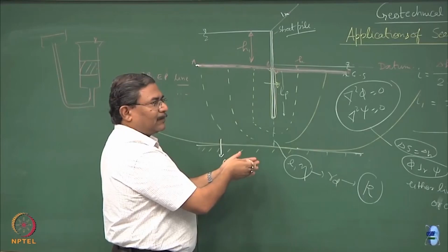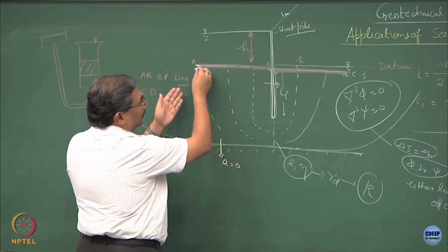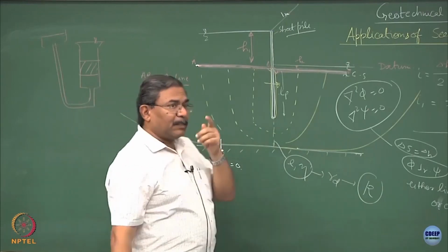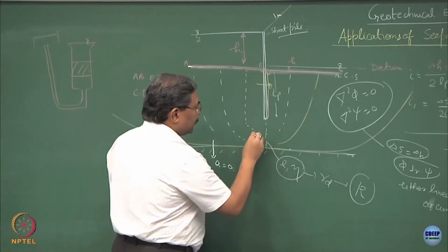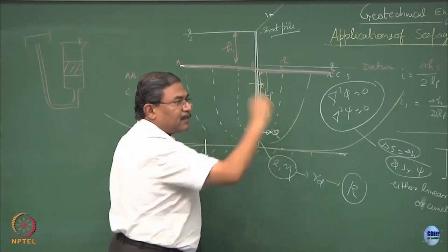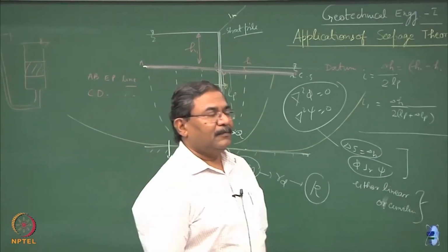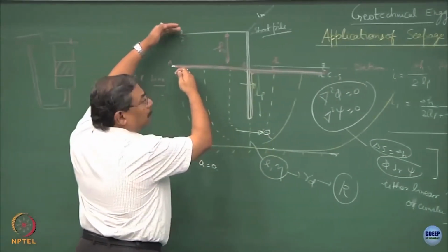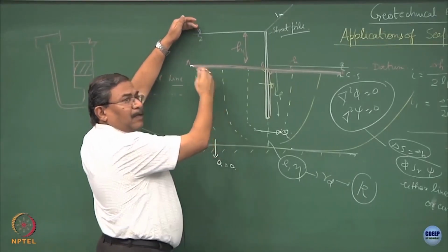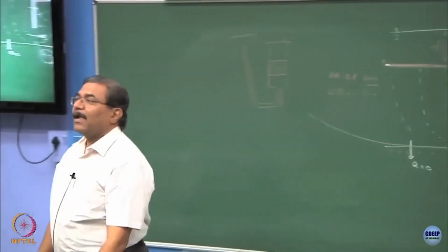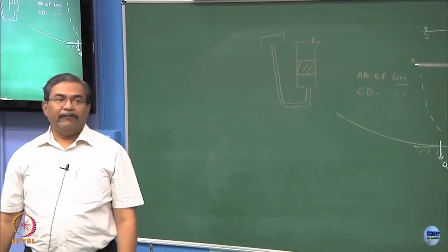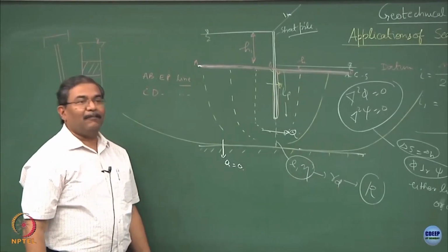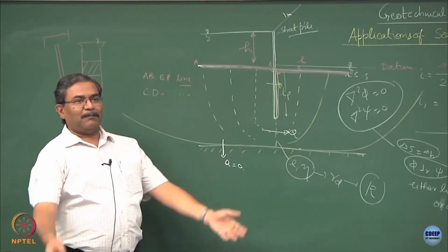One is okay, we have established the flow net. So, all these become the flow lines. The whole idea of doing this flow net is, as somebody said correctly, I want to find out what is the discharge taking place across the sheet pile system. Because what is your whole intention? The whole intention is that this water should not be lost at all. Polavaram Canal is a beautiful example, clear. You have a lift irrigation system, pervious land, even if you store water, everything will seep through. What is the point in spending crores of rupees?